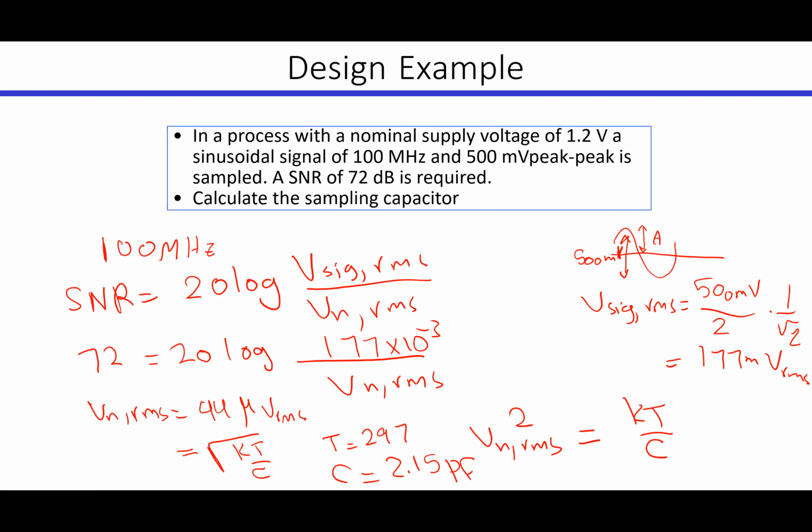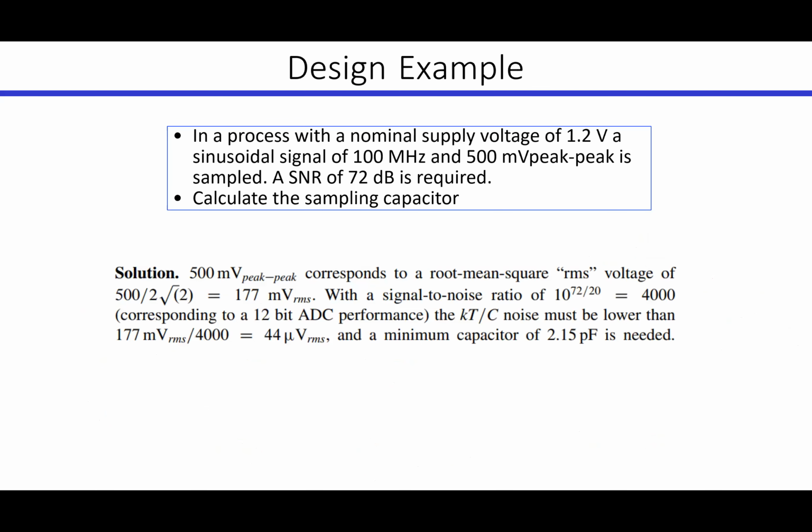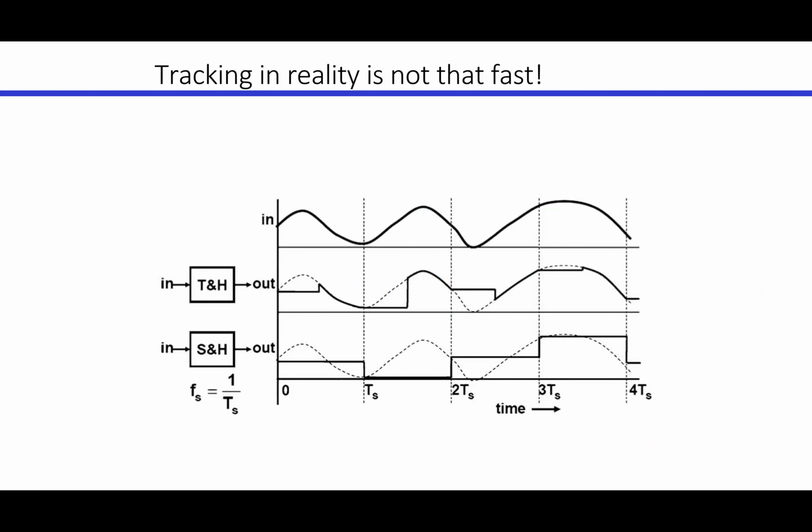It's just mentioned here for the sake of it. But if I asked you, for example, what should be made less, here I'm giving you the SNR, but what if I gave you a different value? I told you that I want to select my thermal noise to be less than my quantization noise for this certain number of bits. Then you will need to use that supply voltage, assuming that it is your V full scale. Okay, so I just solution.